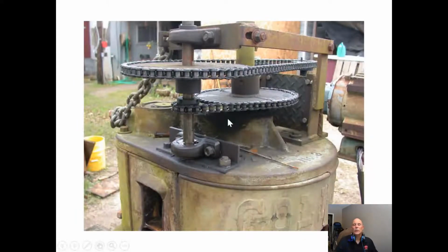Now we get all sorts of different gear combinations to do different things. We can increase these, we can decrease these. This is why we're able to move large amounts by just using a gear ratio. And again, you take a look at, for instance, a highway truck, a B-train that's fully loaded with lumber, and we put it in low gear, low range, and we get a tremendous amount of torque. But as we start to increase the speed, we want to shift our gears because we've got that load in motion, and it's easier to keep it in motion.